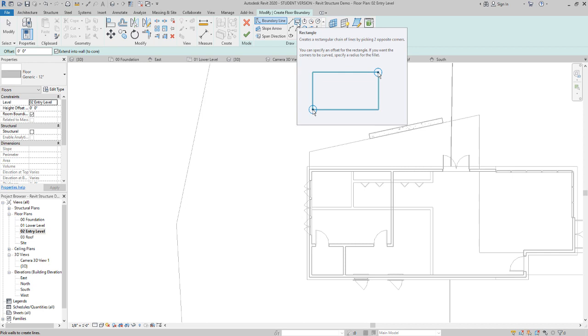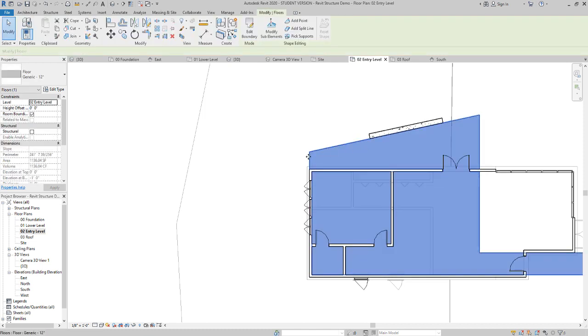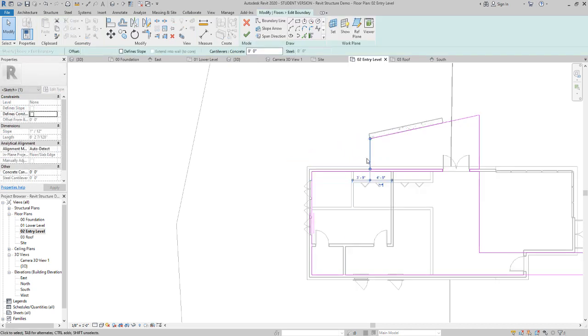I'm just seeing if there's any extra. Oh, I see. Okay, so I had messed up. Let's hit the X on this floor sketch, edit boundary, click this guy. We're just going to move this thing up. Actually, I'm curious, maybe this was the edge. How far was that supposed to be? My apologies. So we're going to edit the first floor. Ah, so they had changed it. It's basically in line with this edge here. So I don't even need a specific dimension, they just want us to ballpark that.